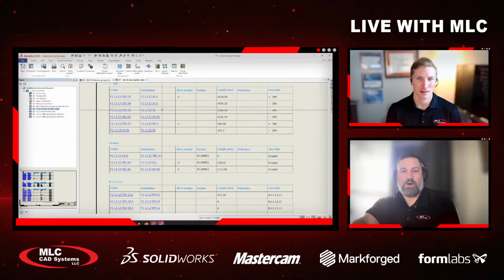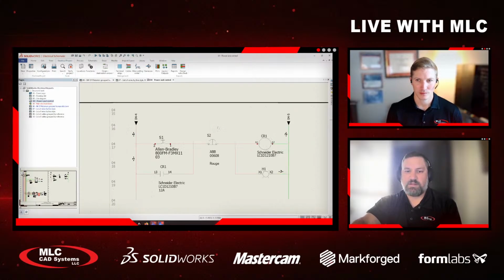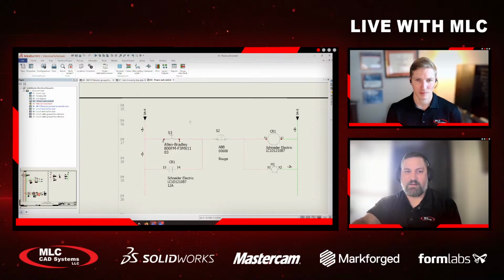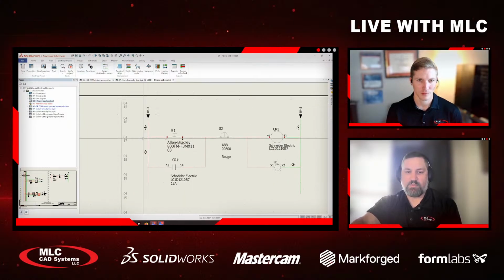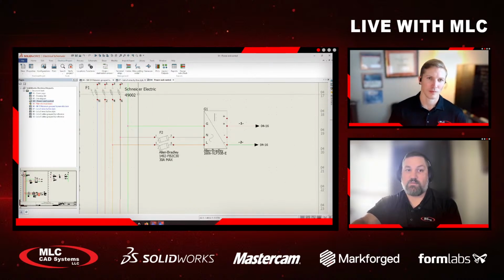Now, numbering of wires is something that a lot of customers don't do because it's simply time prohibitive. Inside SolidWorks Electrical, that is not time prohibitive because it's pretty much instantaneous. You'll see that we have a couple wires here that already have a number, but most of them don't. And to number these wires, it's very, very difficult. I'm just kidding. It's not that hard. We're going to say number new wires.